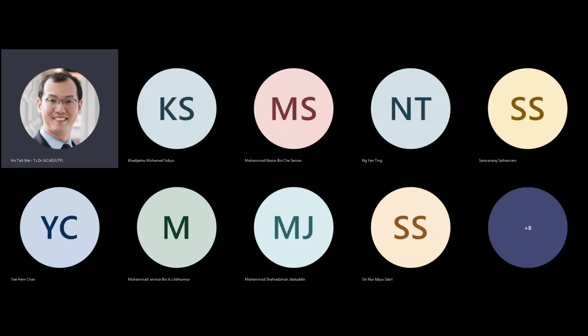That is because you apply a voltage here, the voltage is like 1 volt, 1.1 volt, but if you actually look at the electric field, which is a ratio over the actual distance here, the electric field is really, really high. It's on the order of thousands of volts per unit length, and that electric field is putting in a very strong force, pushing the carriers very close to the surface. So it's like the carriers are trying to move in this dimension, but they're being slammed vertically this way, and that slows down their velocity as well. So this is the velocity saturation effect.